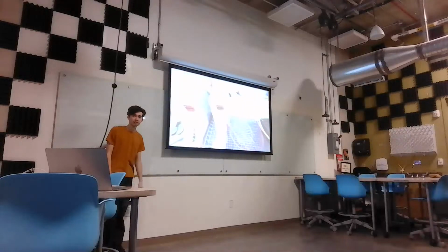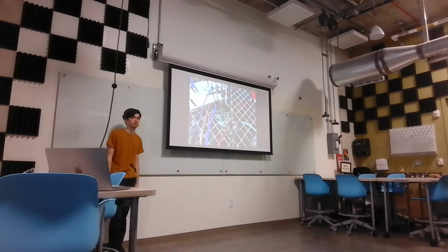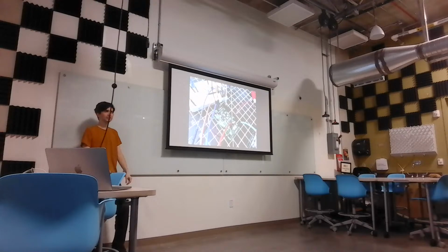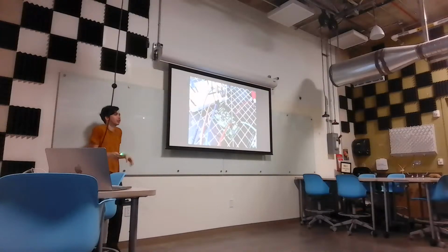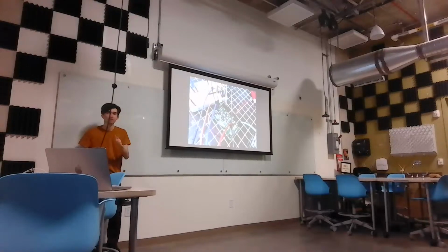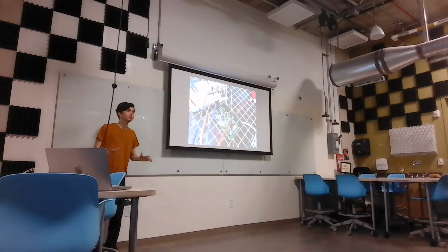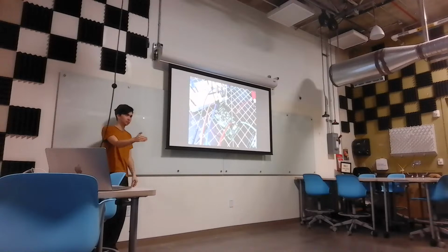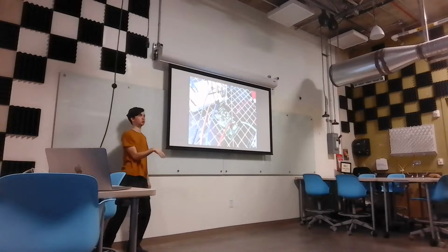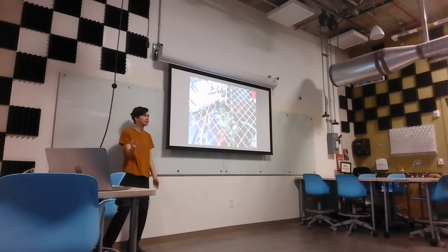The result of not having them is crazy oscillations. Literally, I plug the board in and it would make the sound, and then it would just shut off. So finally, I realized that. The reason it took me so long is because this system is so high frequency that when I'm thinking about voltages propagating around this thing, it's like molasses sloshing through a tube. The time matters.